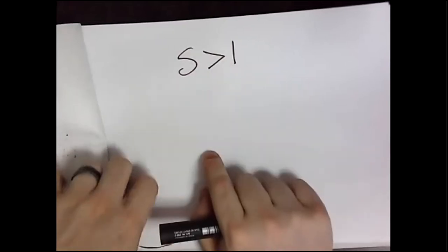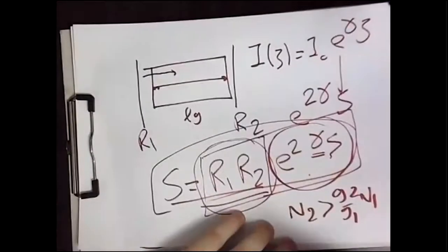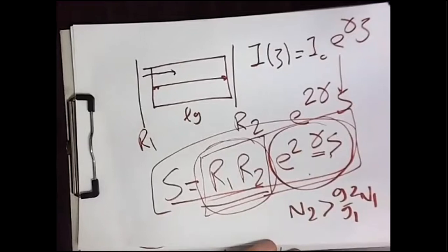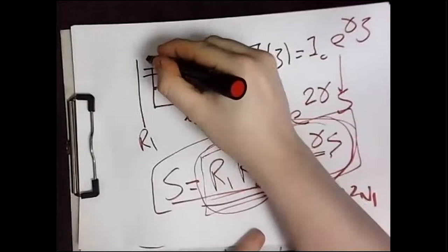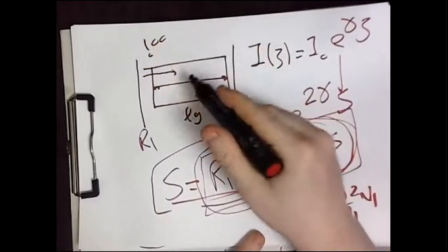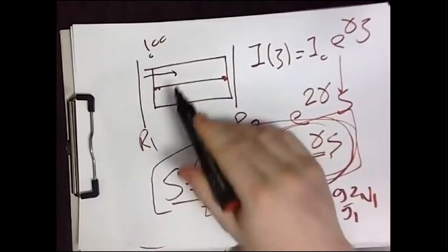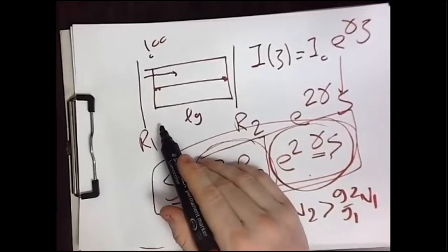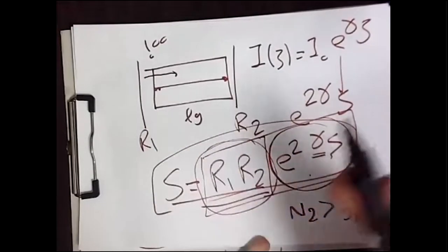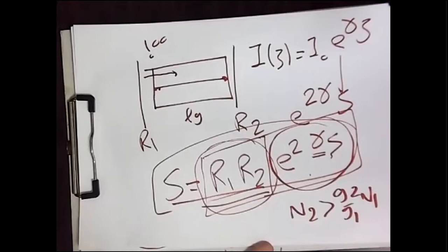In this case, you have a gaining medium instead of having a losing medium. If you remember the example I delivered in part 2 of lecture number 4, when we started together with 100 photons, and I told you that if this is 80% and this is 80%, after one round trip it will become 64 photons, and we lose 36 photons, if you remember.